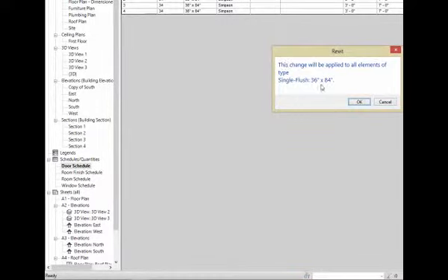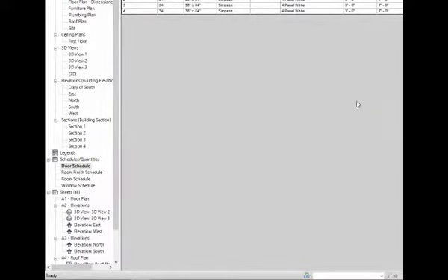Okay, there's different doors. There's doors 1, 2, 3, and 4. And I know the door 1 is a 36 by 84-inch door. Actually, all his doors are about the same size. They're big doors. Okay. If I would like to be able to sort of relate the information in this schedule, because in the schedule, I know this is going to be a Simpson door. And I'm going to make it kind of a 4-panel white door, whatever it is. Okay, I'm putting information into the database about what I want that door to be.